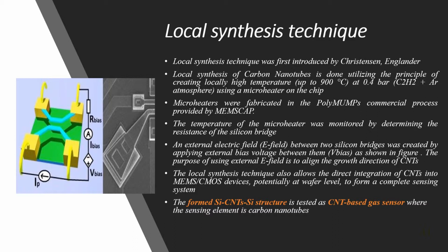Also, an external field between the two silicon bridges was created by applying an external voltage between them, as shown in the figure. The purpose of using the external electric field is to align the growth direction of the carbon nanotubes. And finally, the local synthesis technique will allow the direct integration of the carbon nanotubes into the CMOS devices, potentially at a wafer level, to form a complete sensing system.